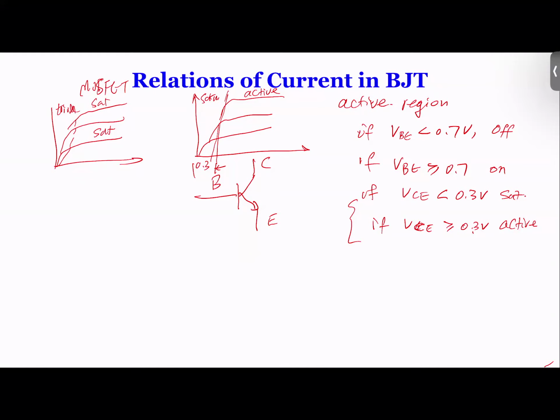Similarly, if you move on to a job where you design an integrated circuit or a simple amplifier for some speakers, when you design the circuit, you need to check whether the transistor is in active mode. If it's not in active mode, your design is flawed and not going to work. So even though most of the analysis moving on will focus on the linear, active mode, we still need to understand how to make the transistor work in that mode. Okay, clear? Good.